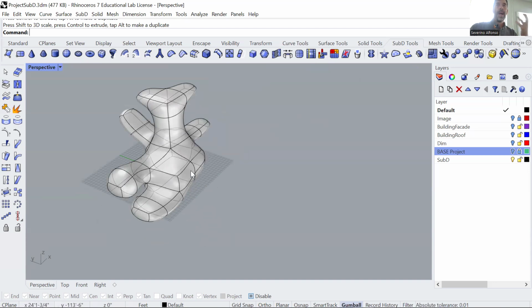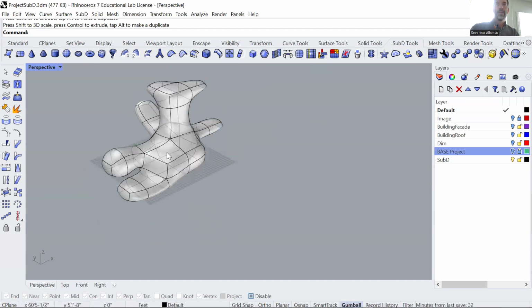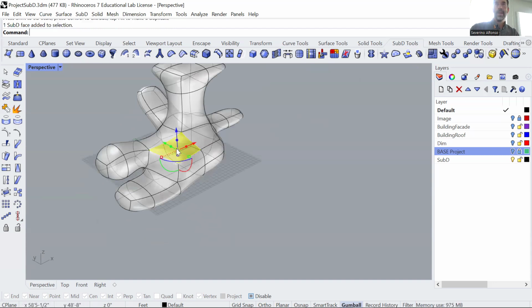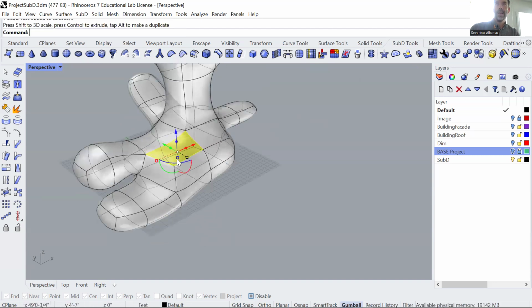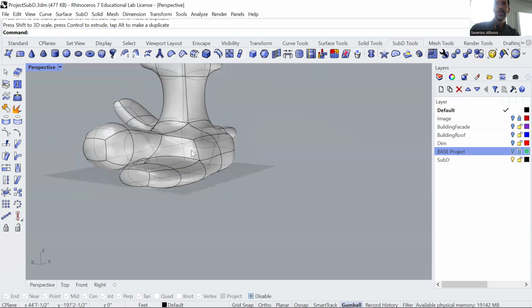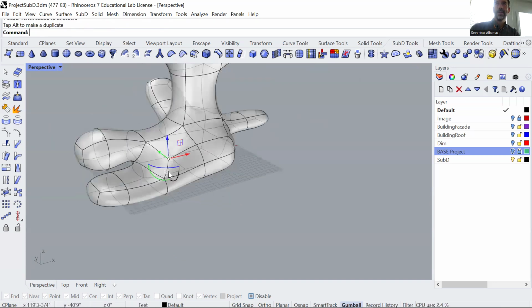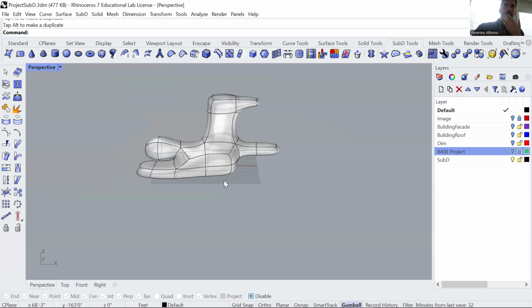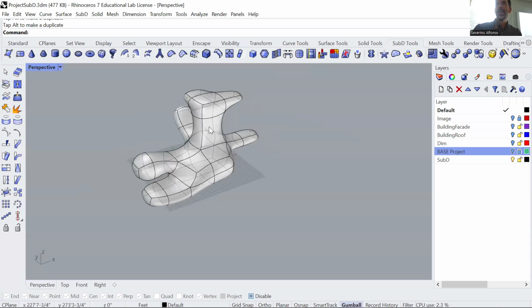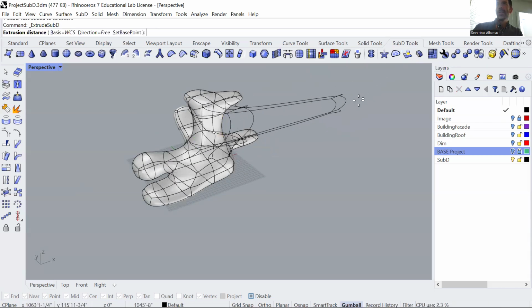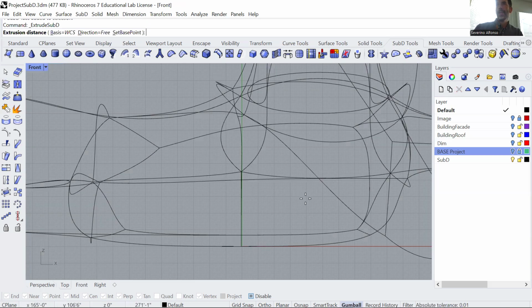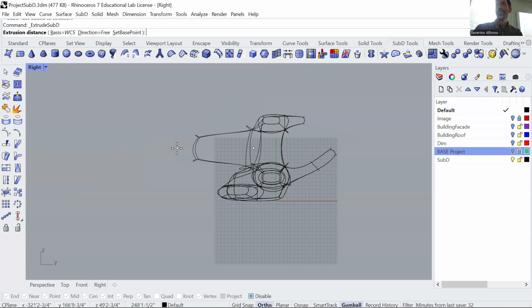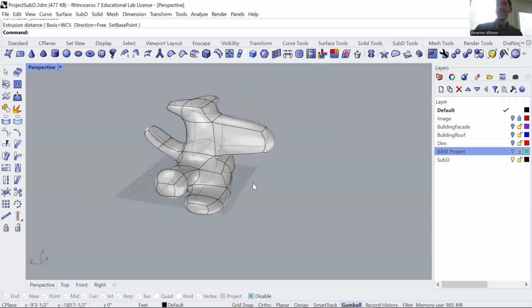you end up having, it's worth working a bit on the aesthetics of it. You can slightly scale some of the faces or slightly push some of the lines to make it smoother in one direction. You can do many things with this. Obviously, you can combine the bridges with the insets. There's also the extrusion option, which is similar to the inset, as it creates an extrusion, which is the same as inset.